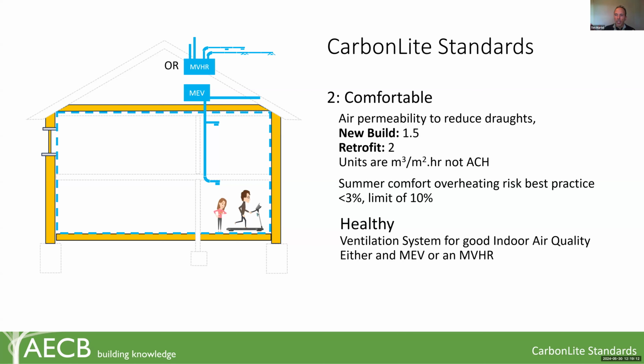That means that the infiltration is much less, and therefore we have to have a separate ventilation system for good indoor air quality. So that can be MEV or MVHR.